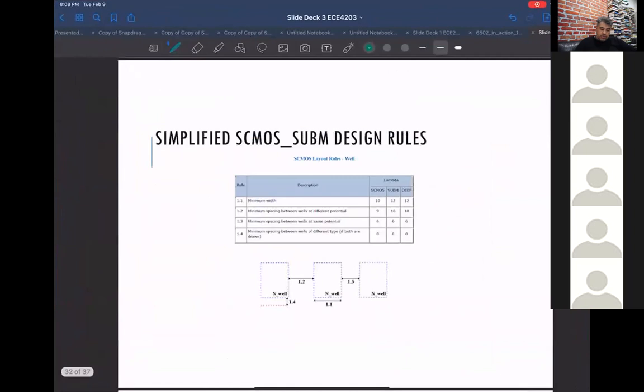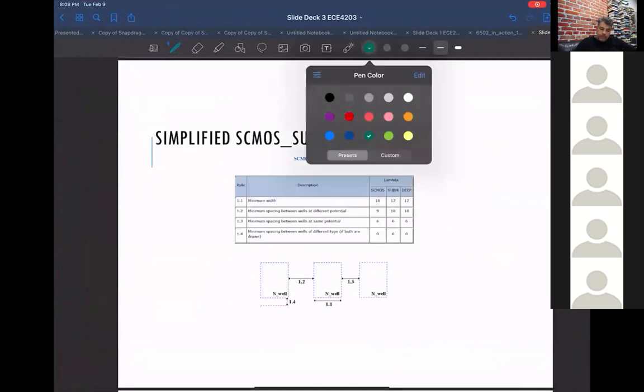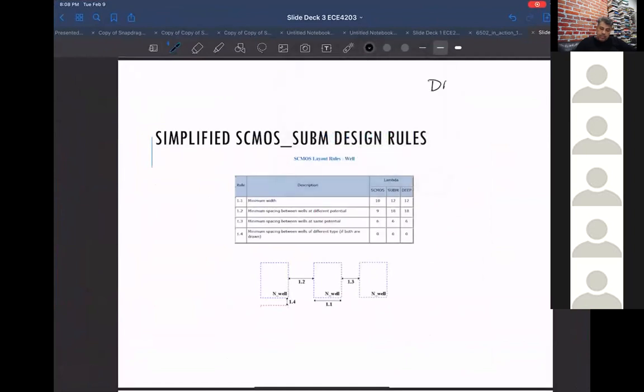Okay, so you have a tool called DRC, which stands for Design Rule Check. Using the software tool, basically all these rules are put into this tool, which then checks them against the layout you've drawn, and it tells you if you've made any mistakes.